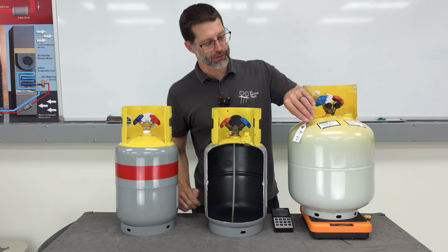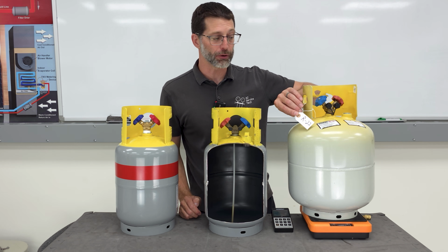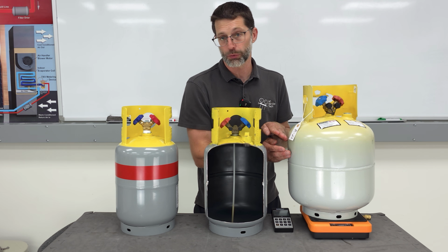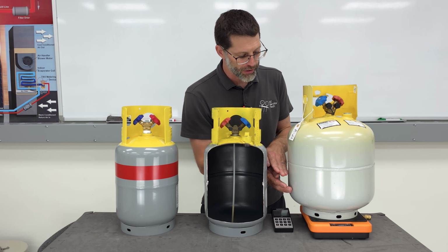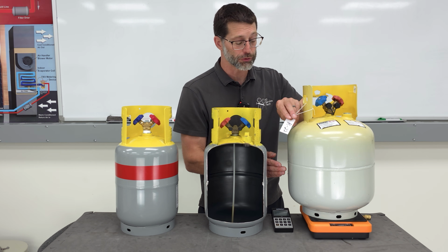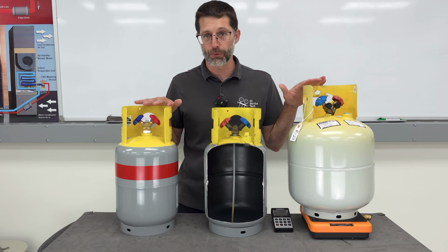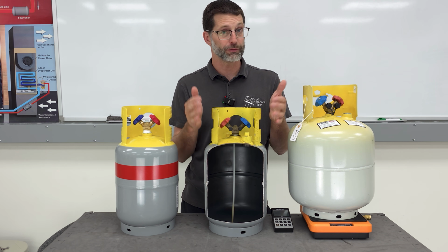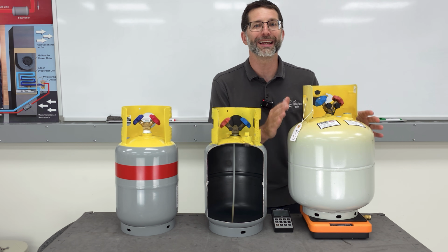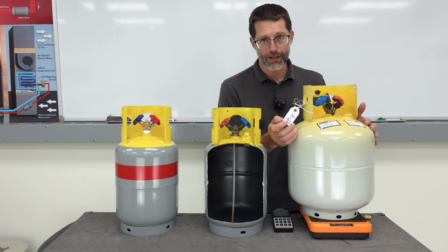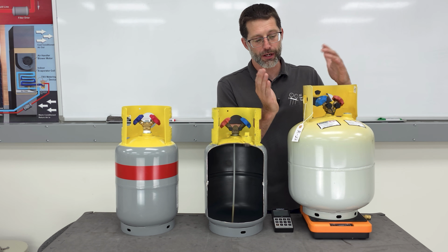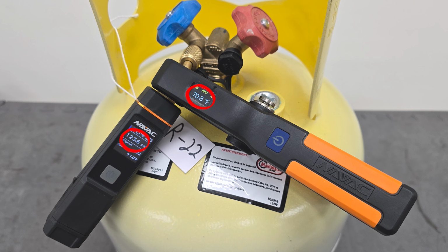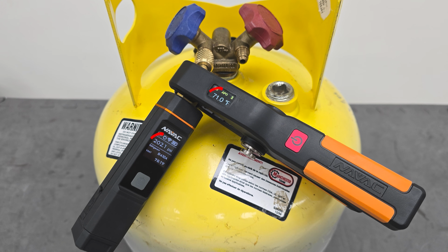So you want to make sure that you're only recovering one type of refrigerant into that bottle. You could recover multiple systems as long as all of them had R-22 in them. You could put one charge on top of the next, on top of the next, as long as they're the same refrigerant, R-22. So you want to have your tanks labeled, especially now that we have refrigerants that have similar pressure-temperature correlations for the saturated refrigerant. It was pretty easy before if you didn't have a tank denoted and you wanted to know if it was R-22 or R-410A, because at 70 degrees, the pressure would be, say, 121 psi if it was R-22, but at 70 degrees for R-410A, it's 201 psi.